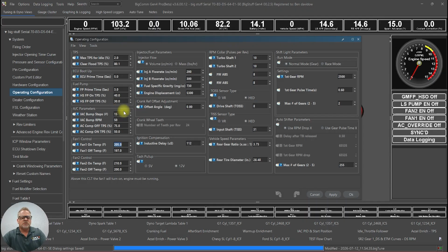It's been around forever. If you just have the key on with our system, it will not turn the electric fans on. Okay. Electric fans have to see over a couple hundred RPM. So this way, with the key on, the fans are just not blasting, just running based on the temperature. If the engine's been running and you just turn it off, and now you're sitting there with a warm engine, okay, this is where you configure the fan on and off temperatures.